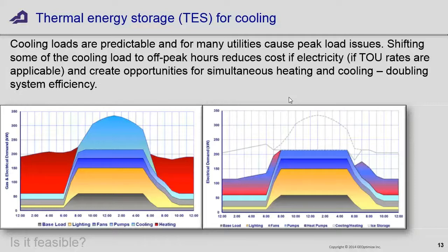And if you happen to have time of use rates available, that's a bonus. The numbers that I've been seeing on these kinds of systems, if you're using the heat pump capacity, for example, that store in Denver has got 350 tons of equipment in it. That's all it has. It's got about a 530-ton cooling load in real life, but 225 tons of that comes from the capacity of the ice storage tanks that are built into the system. Nighttime, there's very little cooling load. They make ice all night, and then during the day they have the 350 tons of equipment running. When they can't keep up, not if they can't keep up, when they can't keep up, then the ice supplements.